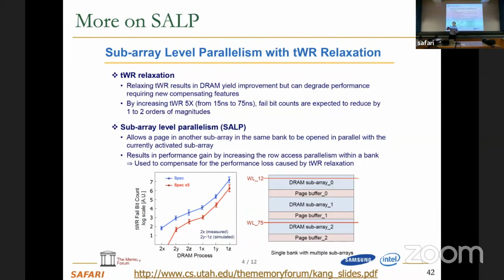Now, if you can do everything in DRAM, it's easier. If you can do everything in the memory controller, it's easier. But this changes the memory controller, DRAM, and the interface, right? So that's one of the main reasons why it's difficult to get some of these ideas adopted in the standard, at least. So if you want to do a non-standard DRAM, I think you can design your own controller and DRAM and do it, I believe. And I think more people should do it, frankly.